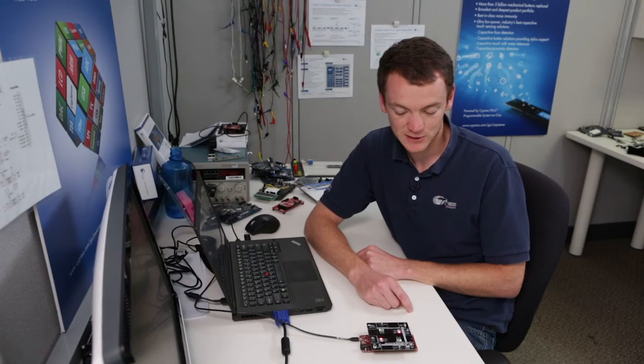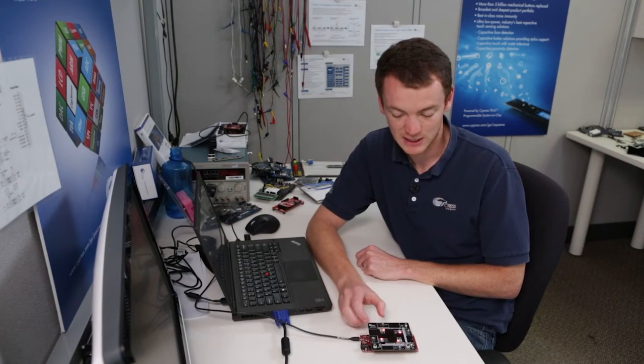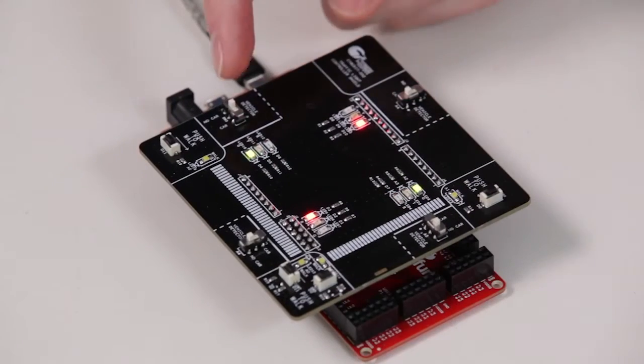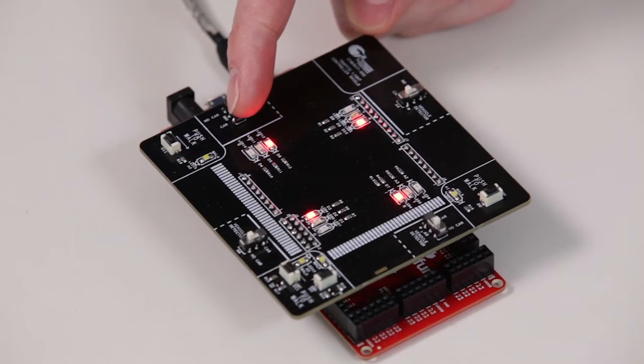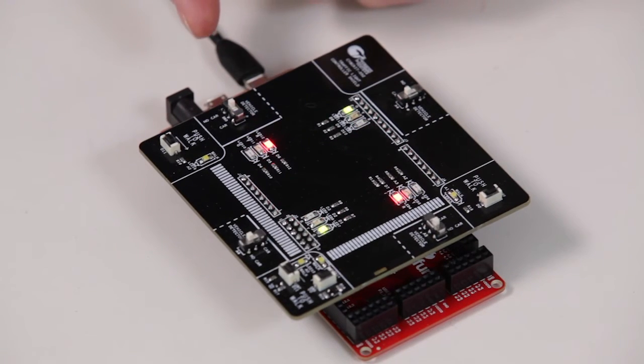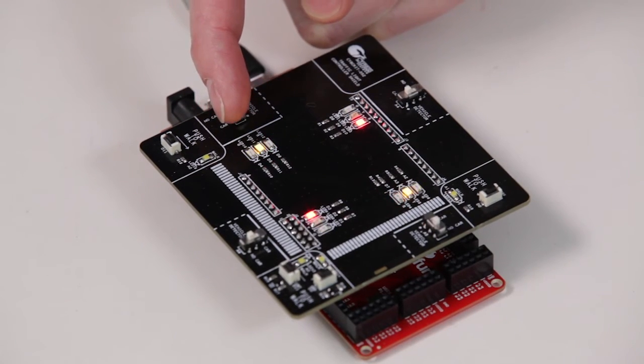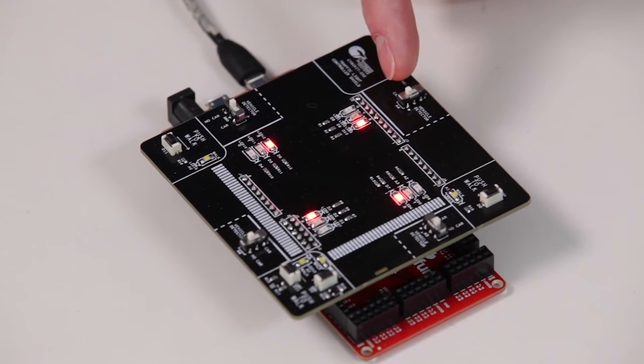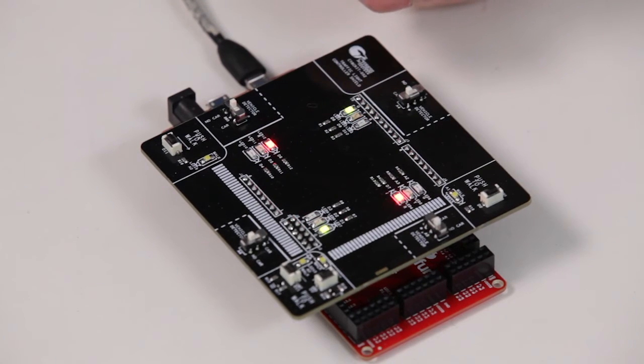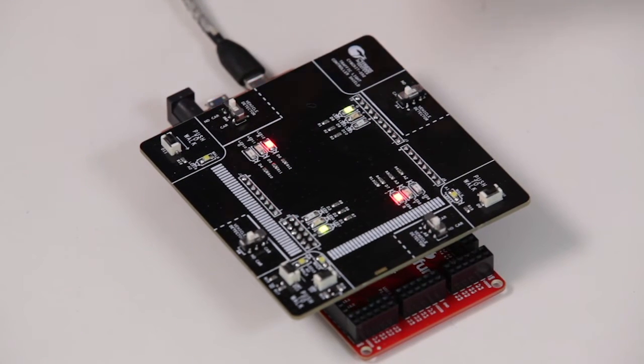Okay, so then the other feature we talked about was the vehicle detect. If I flip this on, you'll notice that the green light turned off a lot quicker that time. So let's go through the whole thing. The green light is on very quick because there's a car here and it wants to go and there's no other cars. So that makes this intersection a little bit more efficient.